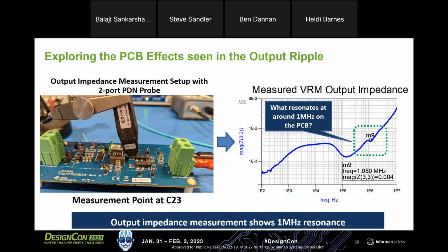The vector network analyzer sends one signal through one pair of probes, receives the signal through the other set of probes, and does the transformation between the S parameters and the impedance. One beauty of this measurement is that it will work with power off and power on, meaning it doesn't need any supply voltage to work. But also, since it's an S parameter based measurement, it offers really great calibration capabilities that allow us to measure very low impedances and also up to very high frequencies. And so all of that is supported pretty well. So I hope I answered your question better this time.